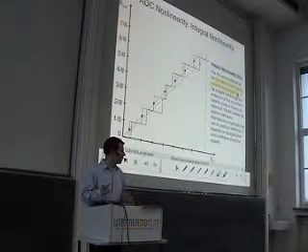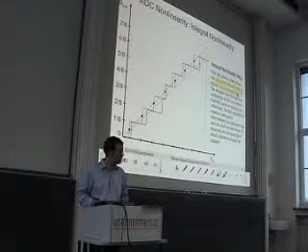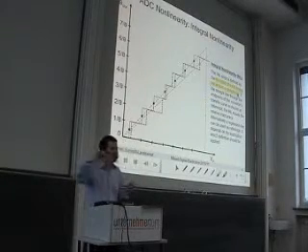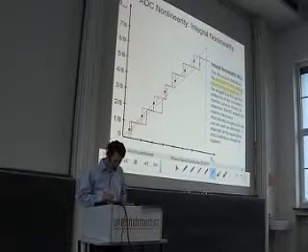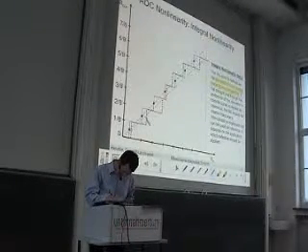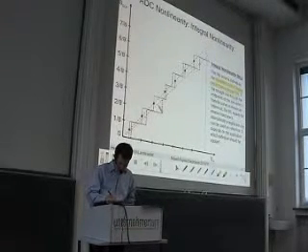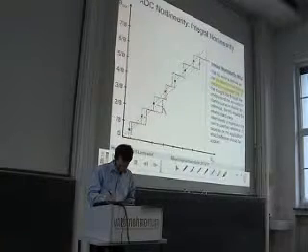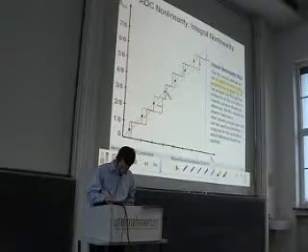So if we use our definition, then of course for the first and the last point the error is 0, because we draw this line exactly through these points. For all other points we can define this. We can say, okay, here is my actual value, and the difference compared to this straight line is my nonlinearity error. The same is here, or here.